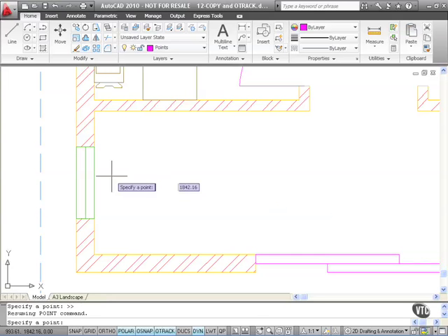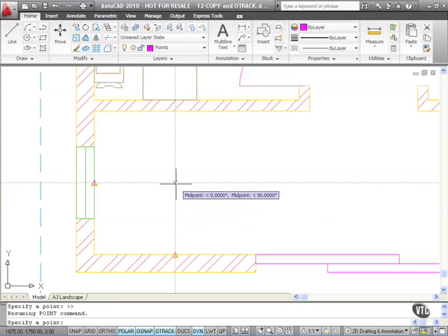So, I hover here. See the midpoint snap of the window there? When the midpoint snap appears, do not click. Just hover. Then, we're going to come down here and hover over the midpoint here of this wall line. Not the hatch line, I hasten to add. Now if I drag upwards now, see the polar tracking line kick in? But as I approach where the midpoint of the window is, can you see the intersection of those two midpoints? That is object snap tracking using those two object snap tracking points to let me know that I have an intersection there where I can place that point.